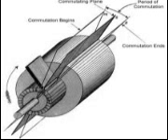Types of DC generators. There are three types of DC generators: series wound, shunt wound, and shunt-series or compound wound. The difference in type depends on the relationship of the field winding to the external circuit. Series wound DC generators. Generators in airplanes have field windings which are connected either in shunt or in compound.